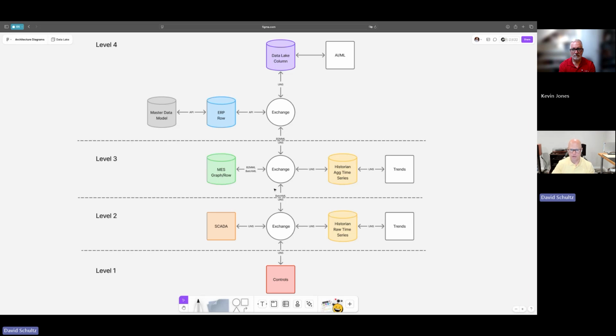Well, now we have better thoughts around how we want to do these types of things. And that's, again, speaking to the power of a unified namespace. The master data model isn't just for the enterprise, it's for everything. And it also allows us these exchange mechanisms. If we can do that in an event-driven, pub-sub way, with MQTT and/or Sparkplug, those are a quick way to get it. But the point is it's already structured. So when it lands in your data lake, even though it's unstructured data, the more structure we can get to it, the faster we can start realizing value with it.